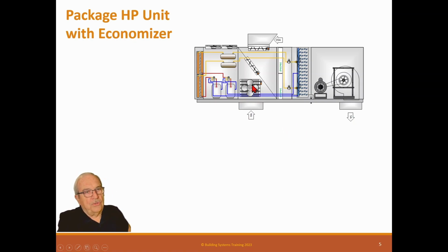Now this one shows an exhaust fan on this relief. And the reason is when we're in regular mode without any of this on, the air goes out, comes up, and goes through this return air damper back to the unit. So this supply fan is running all the pressure to be able to circulate the air in the space.